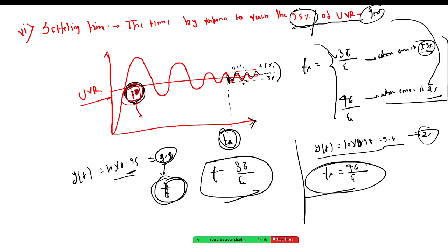And from there, if I am reaching 95% of that, let's say it takes 30 hours to reach from Bangalore to Delhi, then if I take 95%, let's say 27.5 hours or 33.5 hours, in between I'll be reaching there. So I can roughly estimate the time at which I can reach, right? That is the settling time. For the response, this is the settling time, and how much it reaches 95% or 98% of its ultimate value, right?